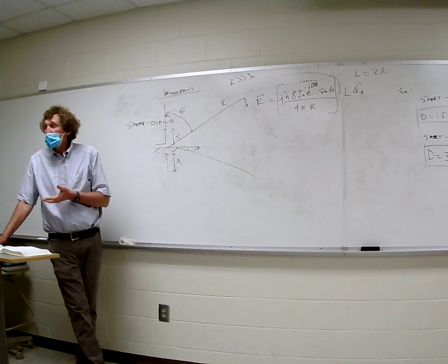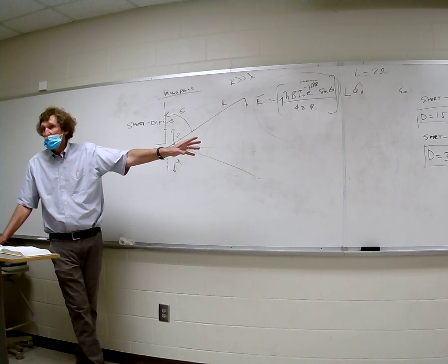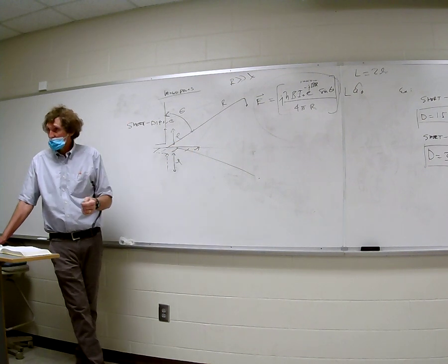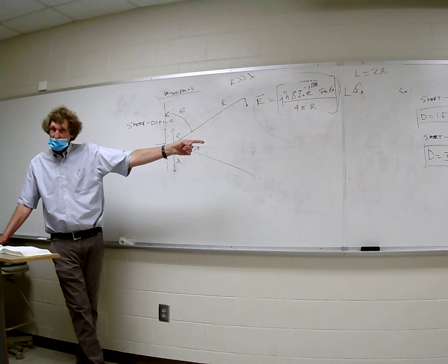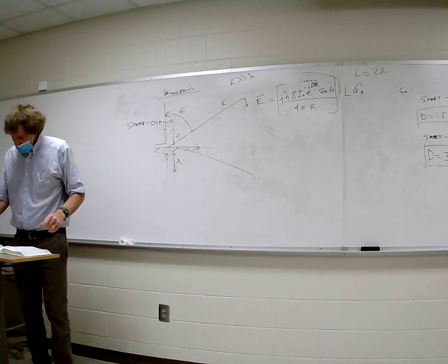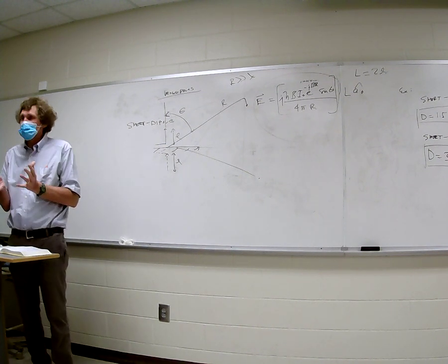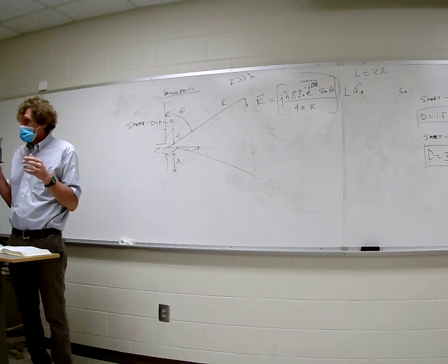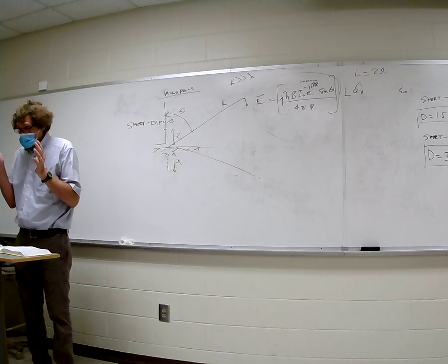And now, so people say, well, why don't I just use that directivity to get the power density? You could, but how much power is radiated? Depends what you know in the problem. If you know the actual current, just get the electric field. If you know the total power, then use the gain. Because that times that gain, or directivity, gives you the power density. Follow me? So, it has to do with that. Okay. I mean, that's like too simple. You take the isotropic power density, and then you would multiply by 3. Any other questions? I'll give you some homework to straighten that out.